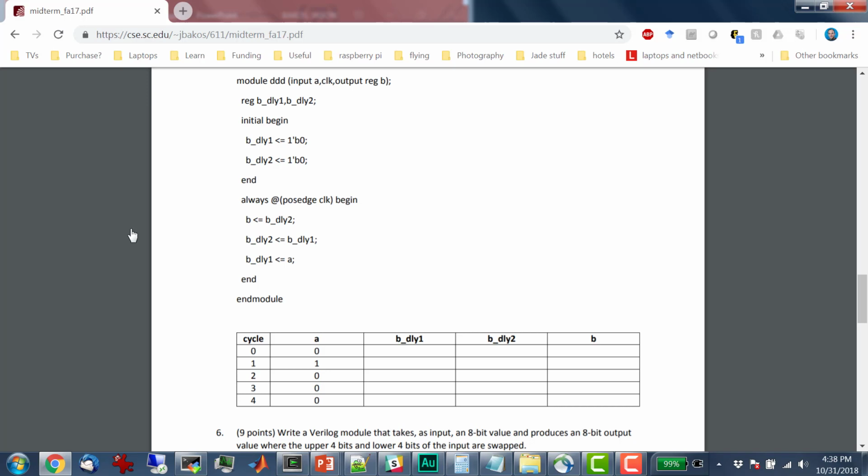When you make a change to the state of a signal on a clock edge, but on that same clock edge, you use that signal as an input, what does the input look like? Is it the new value or the old value? That's the problem we're solving with these two different types of assignment statements. So in this case, in this problem, it doesn't make any difference. You know what I mean?